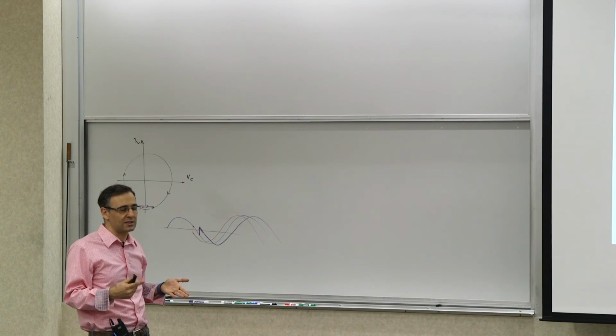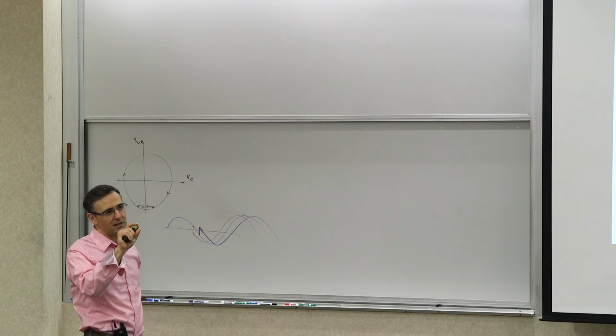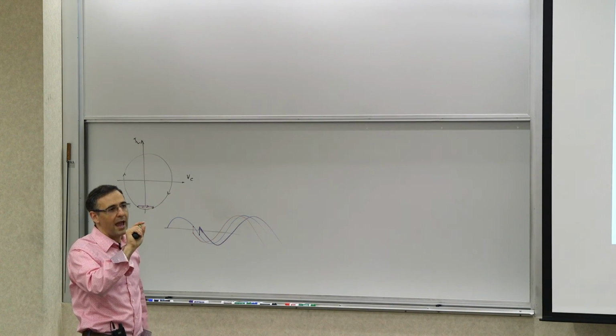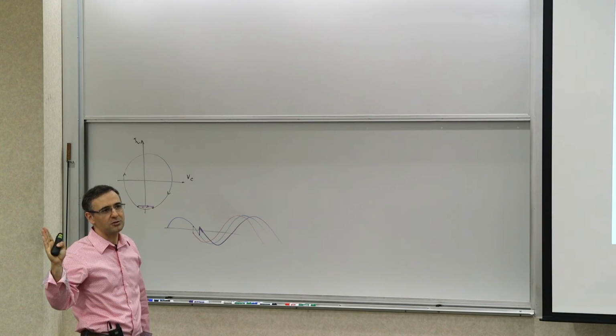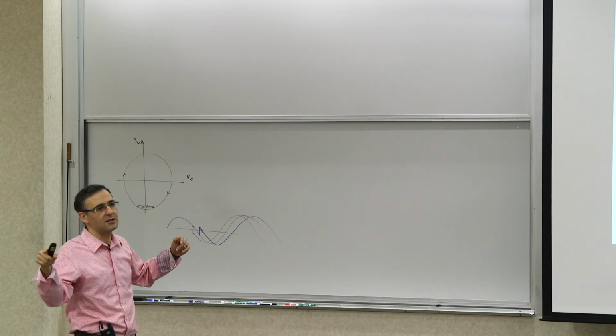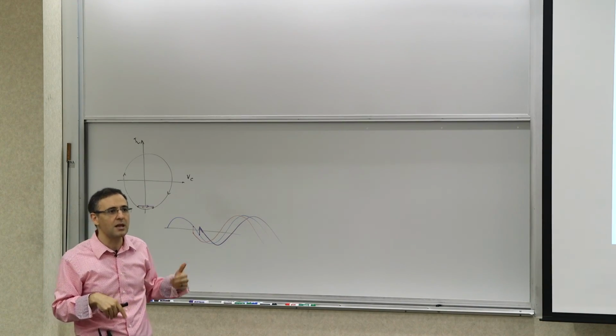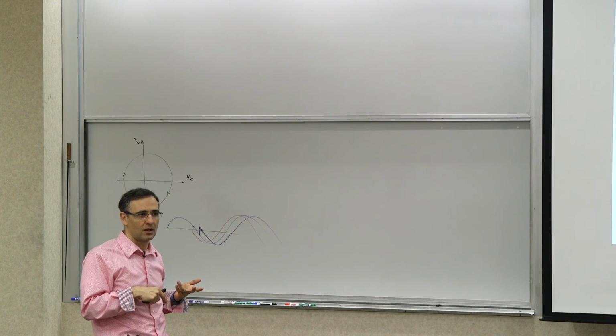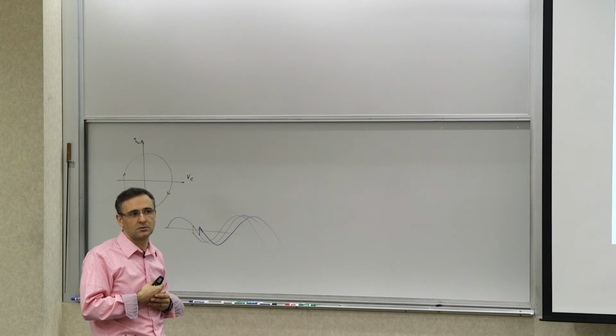The way it works in the simulator is that you hit it with an impulse that's not too large, so as not to drive it into nonlinearity, and then you just sweep that impulse, and you need probably 10 points across one period, and you can generate the ISF off of that. So that's the easiest way. But there are ways to analytically calculate what the ISF would be that we can discuss offline probably.